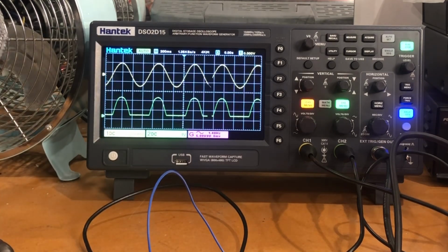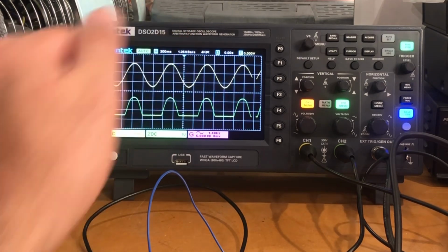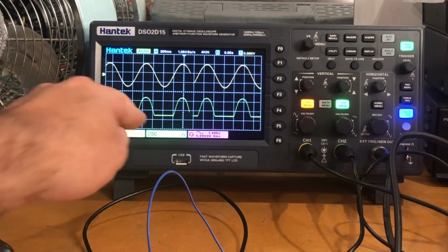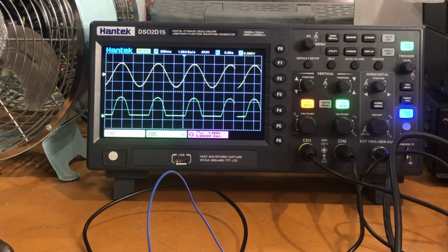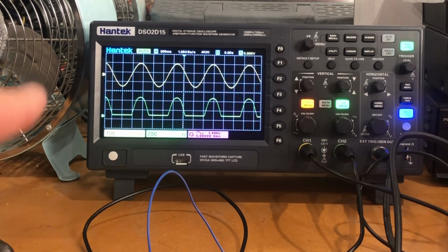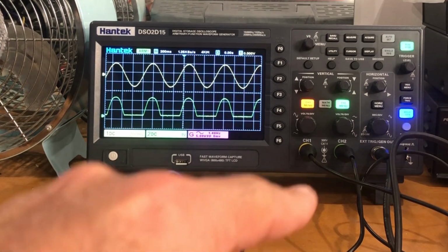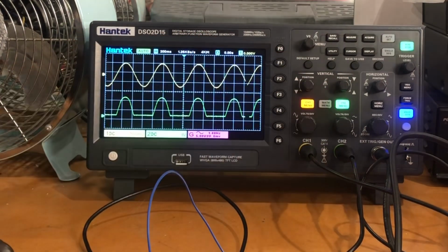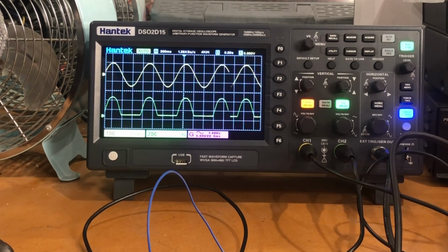And you might be noticing that at the top here, we have a full sine wave. And the sine wave is, it says down here, 1.4 hertz, at 5 volts peak to peak. So it goes up 2.5 volts, comes down to 0, and then goes down to minus 2.5 and back up to 0. And it's doing that about 1.4 times a second, hence the 1.4 hertz frequency.